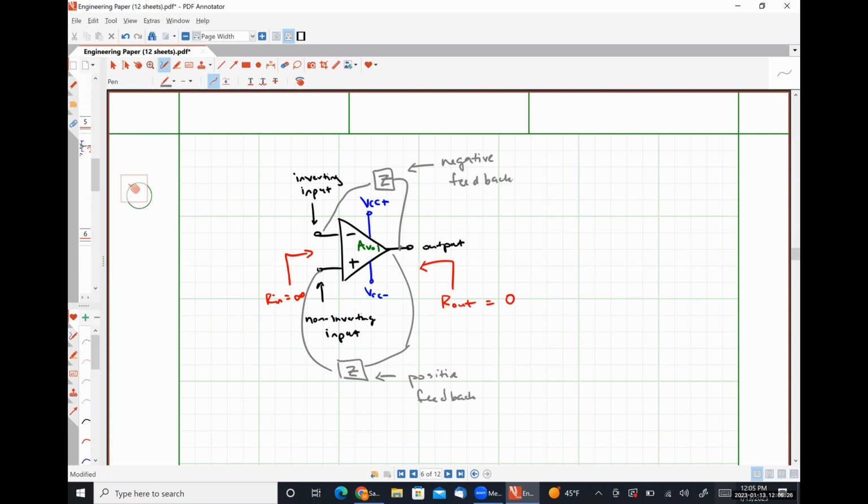Positive feedback is only good for making oscillators, as far as we are concerned. Okay. Effectively, you have an unstable system to where a small increase in your signal level causes a large increase in the output, and then it winds up ringing back and forth between the power supply voltage levels. Doesn't pertain to what we are doing, just wanted to point it out in case you had questions.